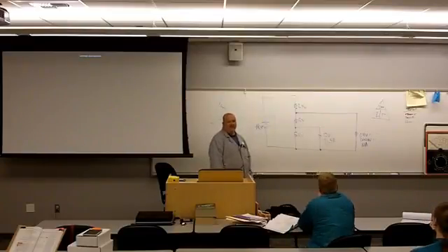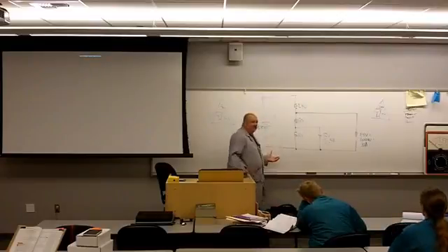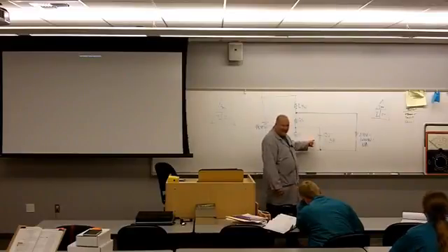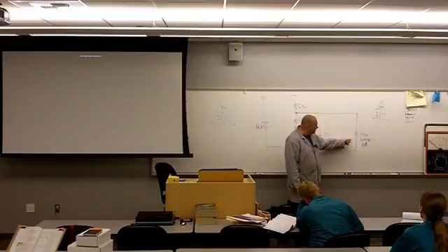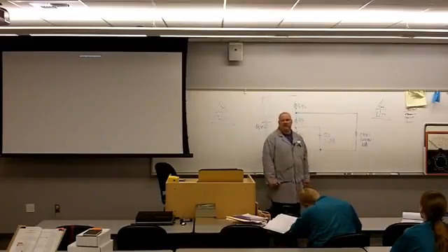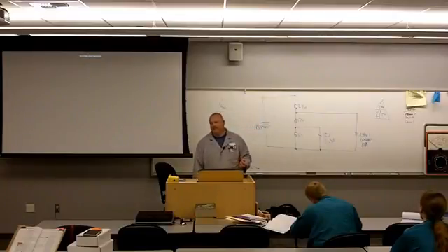10.5. Pounds, ounces, kilograms, amps. I love it when you talk that way. Total load current is 10.5 amps. Everybody see how we did that? The only loads in this circuit, this is a voltage divider, these are my loads. The only loads are a CB radio, and then a radar system. The radar system consumes 10 amps. This consumes half an amp. So my total load current is 10.5 amps. Do you all agree with that?